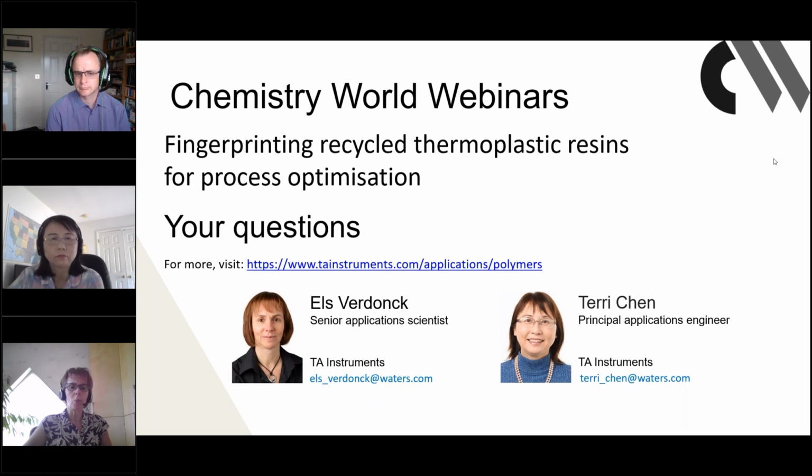If it's more about polymers, then it will depend a bit on what transitions are in the polymer. If the polymer shows a melting peak, typically in the order of a couple of 100 joules per gram, well, at that moment, polymer melting is rather broad, so the peak will be a bit more smeared out than the metal melt. So that means that you will probably roughly need around 100 microgram or even a bit less, and you can detect it. If it's an amorphous polymer that is only showing a glass transition, that is a weaker transition than a melting.